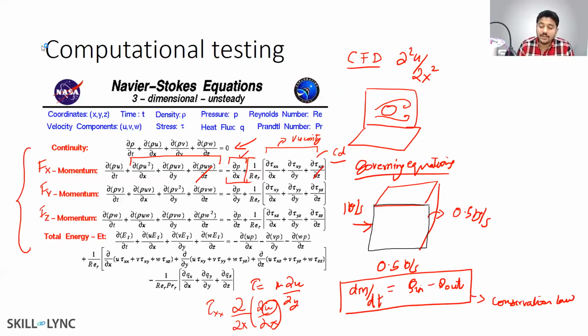Energy, Shahzad, the energy equation is already there. We have total energy, which basically conserves enthalpy. Euler's equation? Well, that's actually wrong. Euler's equation is an approximation from the original Navier-Stokes equations: if you assume inviscid flow, then you get the Euler equation.